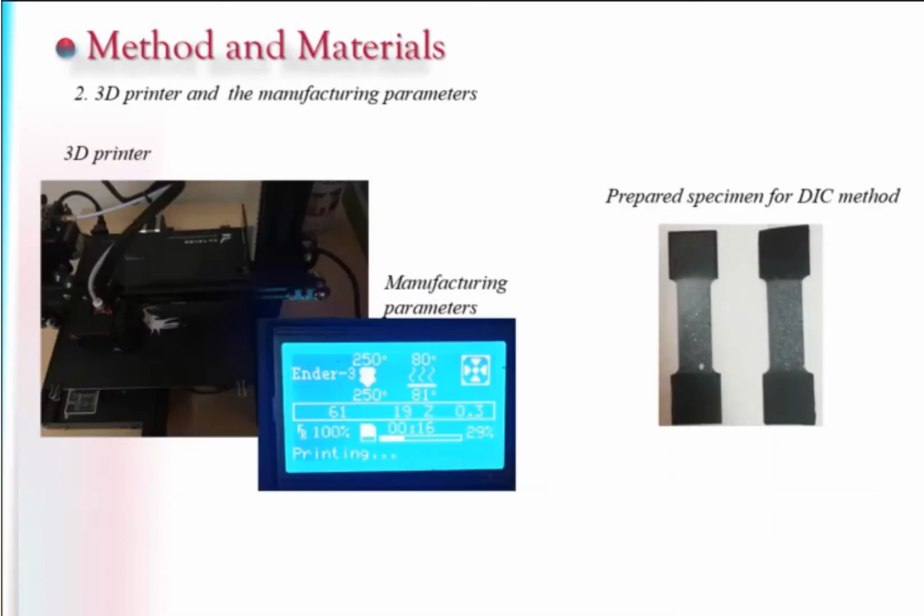In the third step, the machine builds the model layer by layer. The layer thickness dictates the final quality and depends on the machine and process. For fused deposition modeling, a layer thickness of 0.254 mm is typical. For stereolithography, printing can result in a quality of 0.05 to 0.1 mm. The size of a model depends on the machine size.